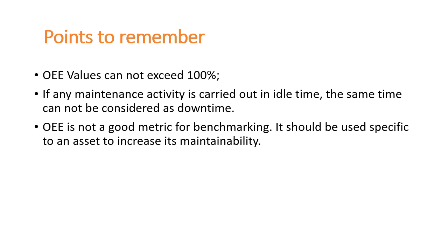So we need to calculate OEE only at plant level and on a specific equipment only, and we should try to improve the OEE value of that particular equipment. We should not compare the OEE value between two machines, or between two plants. It is not actually a very good item for benchmarking. So OEE percentage should primarily be used as a relative internal improvement measure for a specific asset.